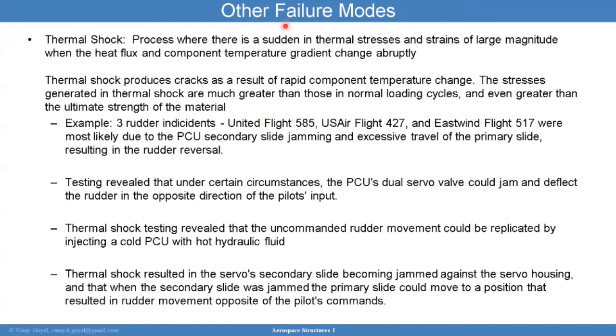I'm going to go ahead and cover now thermal shock. Thermal shock is really the process where there is a sudden change in thermal stresses and strains that are significantly large in magnitude, and where the heat flux and the component temperature gradient can change abruptly. And these changes can produce cracks as a result of the rapid change in the temperature. And the stresses that are generated in thermal shock are much greater than you will find in normal loading cycles, and even greater than the ultimate strength of the material.